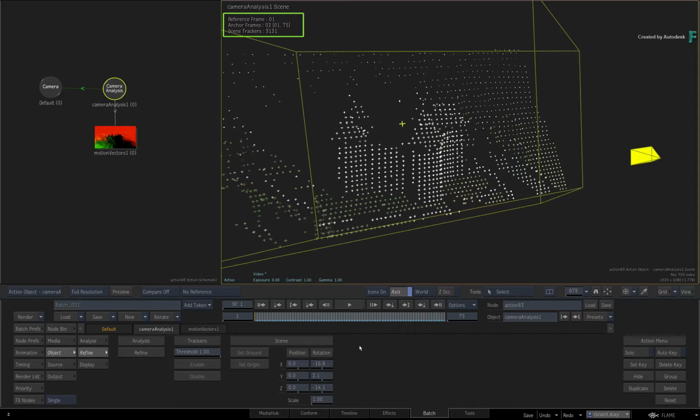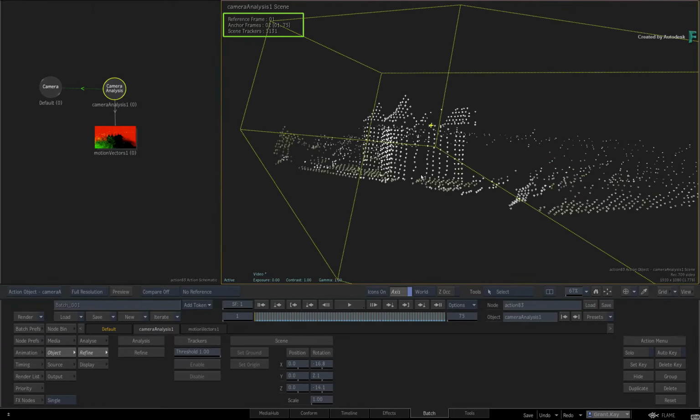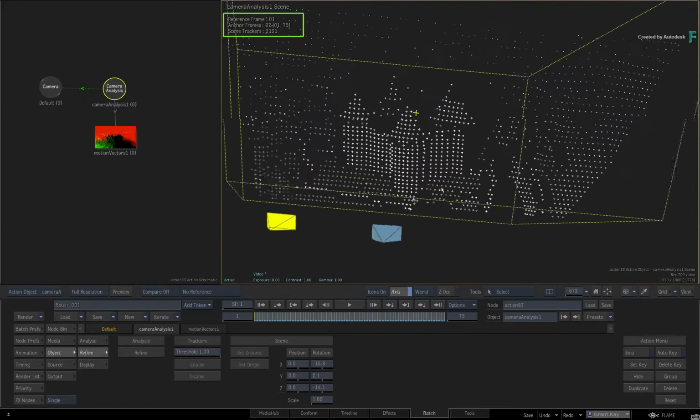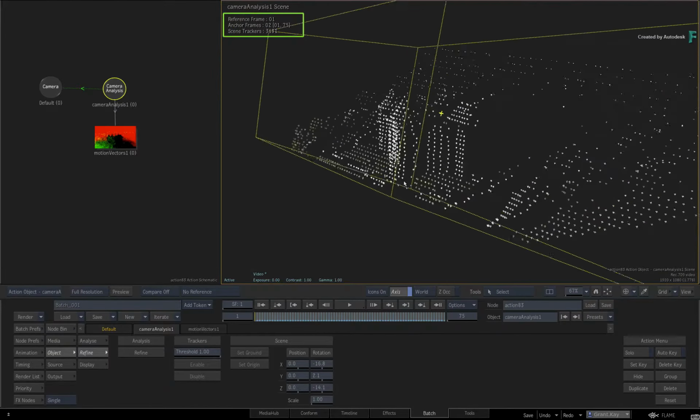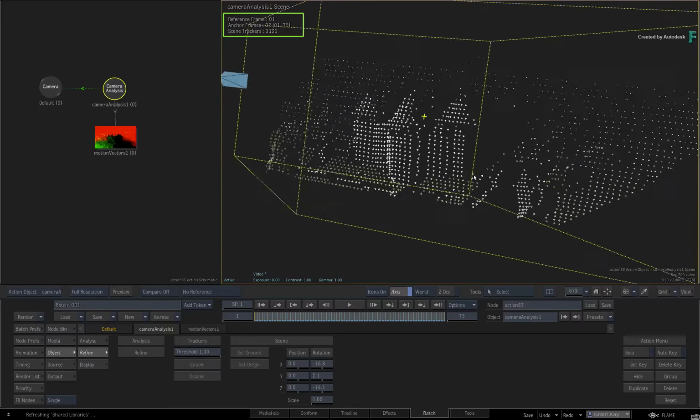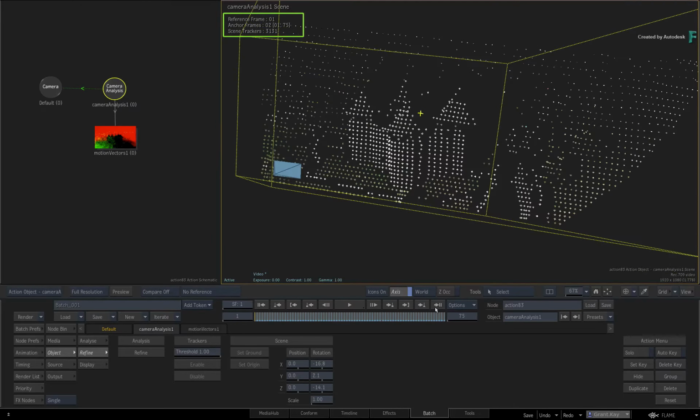So we've returned to the point where the 3D track is complete and the ground plane has been defined within the 3D space. The second option to clean up your image is to generate geometry from the point cloud and project on that. Now, before going down the road of creating 3D geometry, you can also test the point cloud to see if geometry is a viable option.